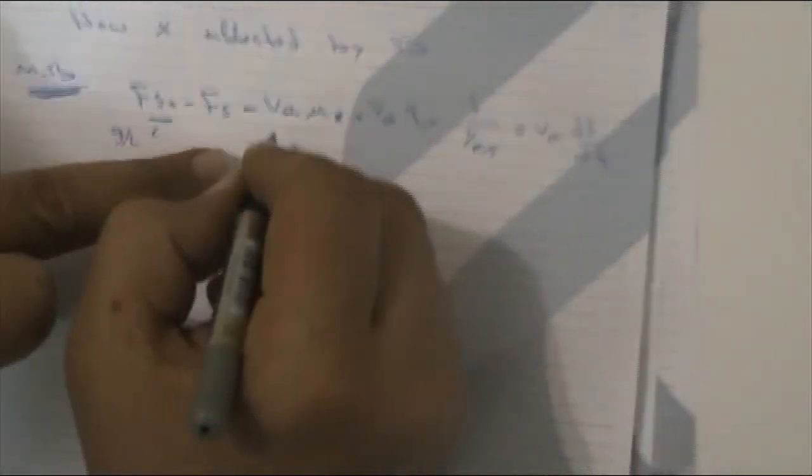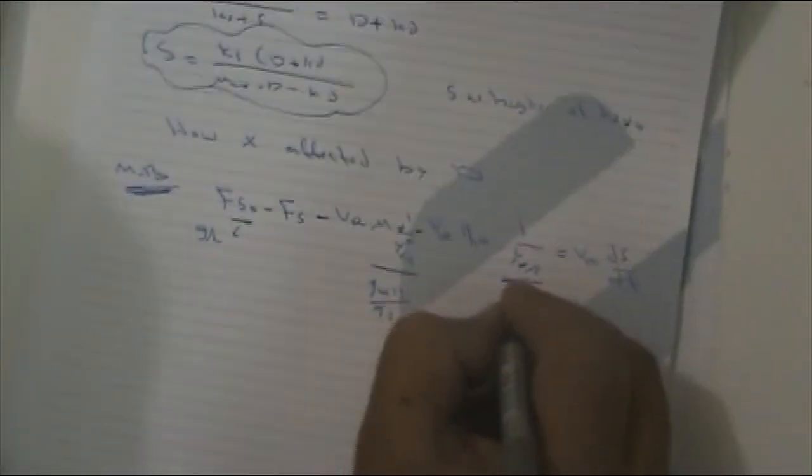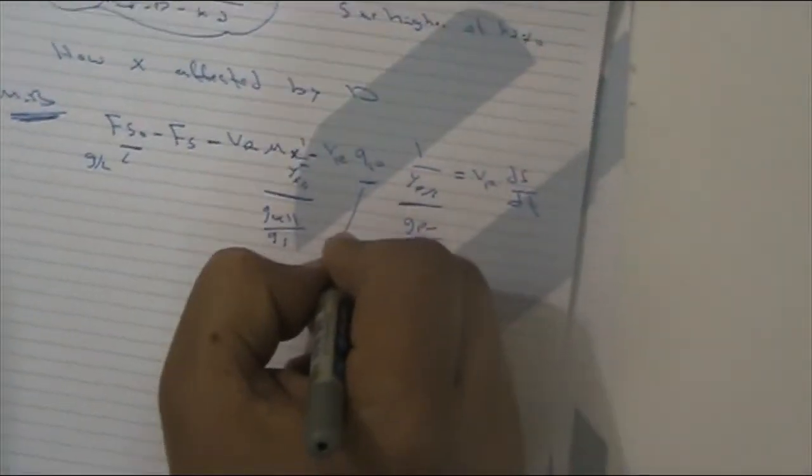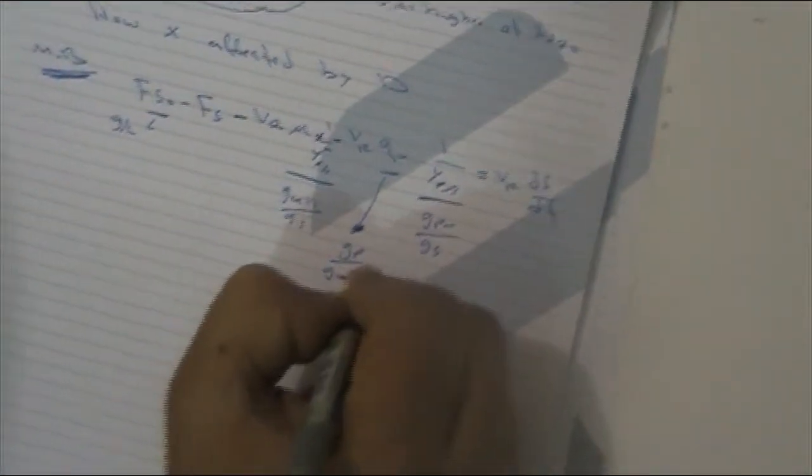Here S naught and S are the inlet and outlet concentrations in gram per liter, and here we have 1 over Yx over s max. Yx over s max is the maximum cell yield coefficient in gram cell per gram substrate. And Yp over s is the product yield coefficient, which is gram product over gram substrate, and the Qp here is the specific rate of extracellular product formation. This is gram product per gram cell multiplied by hour.